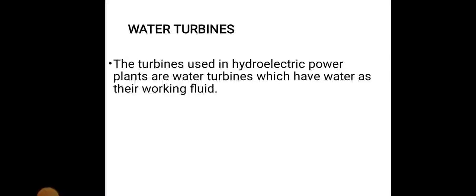Water turbines are classified into two types: one is the impulse turbine and the other is the reaction turbine. Impulse turbines basically work on Newton's second law. In impulse turbines, a number of elliptical half-shaped buckets are fitted onto the blades on the rotor hub. When water strikes the buckets at high speed, the rotor rotates. The kinetic energy of water gets converted into rotating mechanical energy. Thus, electricity is generated when one end of the turbine shaft is connected to a generator.